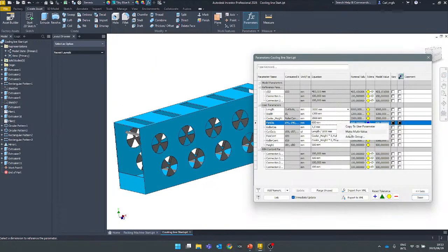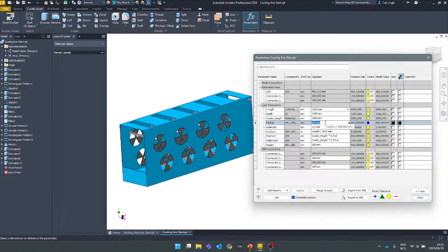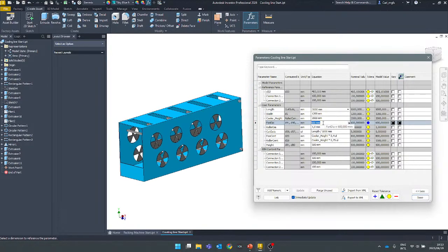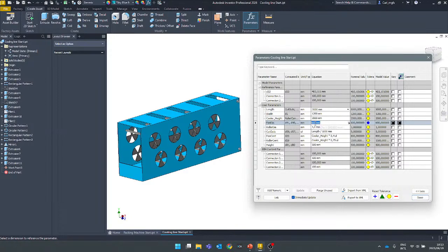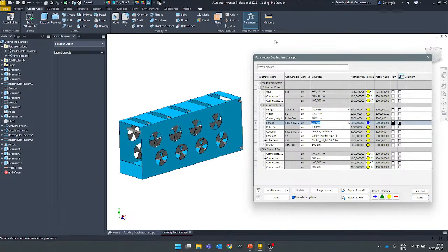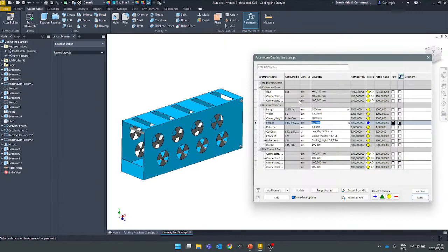Once again, this could be a multi-value to allow the user to choose from a drop-down list, or there could be logic that checks for the size that you input and could warn you maybe it's too small or it's too big, and it adjusts back to a standard diameter automatically. So think about that automation process of the design to create that nice flexible model.